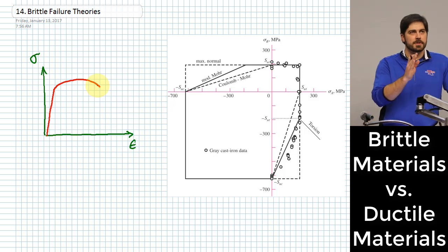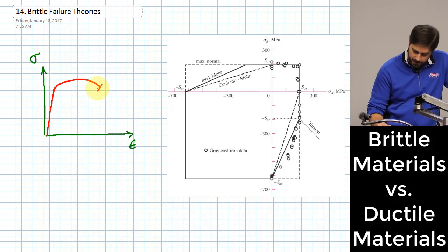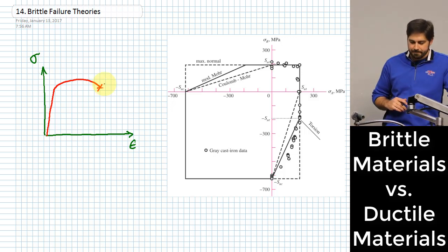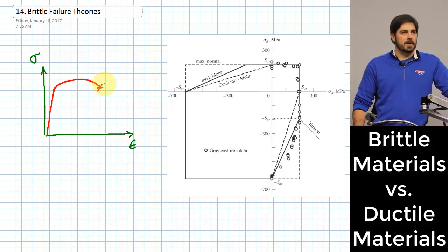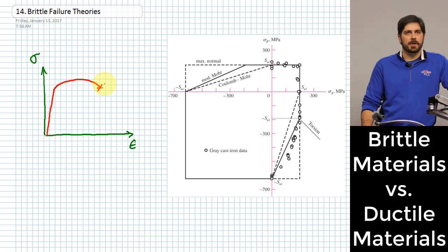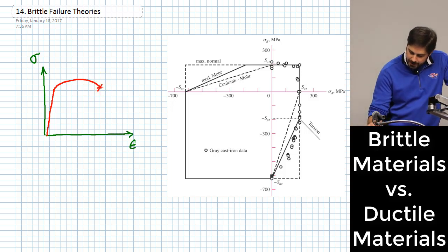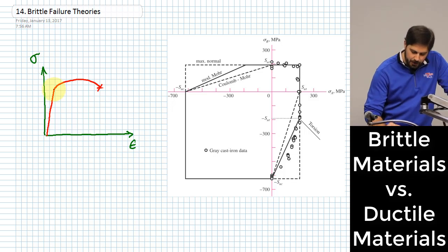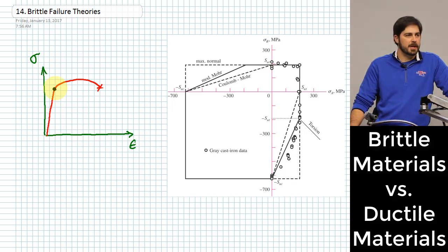The first linear portion is called the elastic region, and then it goes into the plastic region, where it has the curved part up there on the top, and then eventually it breaks. With our failure criterion so far, we have been looking at how to determine when something will fail based on the idea that at the point where it stops being elastic, we count that as a failure.